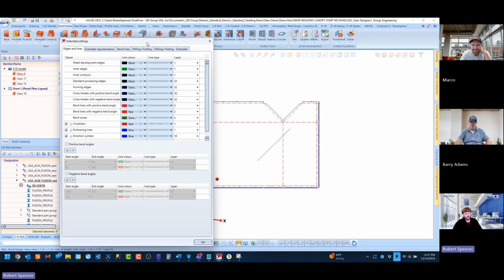So what do you have? You got an outer contour that needs to be a certain layer, probably. I mean, AlphaCam pretty much runs all off one layer. I try to keep everything flat, 2D on one layer, and then control my Z geometries with the toolpath after that. Okay. Does it matter what it's called, or it doesn't? No. The flatter the layer, if it's only one layer, it's a lot easier for AlphaCam.